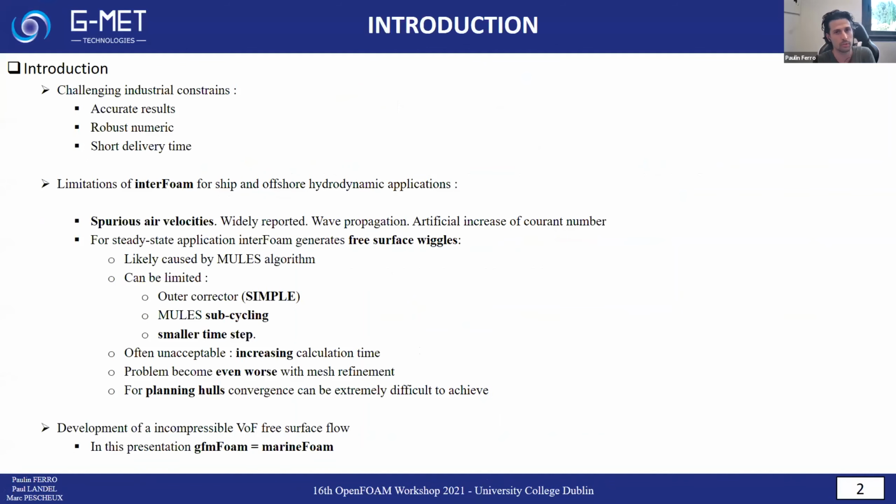So today we are going to speak about naval applications. In an industrial context, we need accurate results, robust numerics, and short delivery time. In this context, the interFoam solver suffers from many limitations regarding hydrodynamic applications. The first limitation is the spurious air velocities phenomenon, which is widely reported in the literature. This phenomenon badly affects wave propagation exercises, and it leads to an artificial increase of the Courant number. For steady-state applications, interFoam generates free surface wiggles.